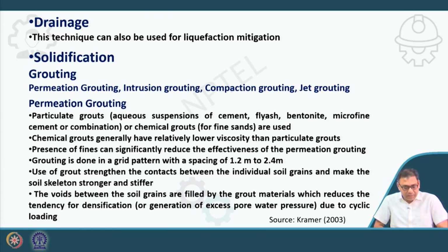Okay, so that means in permeation grouting, the particulate grouts, for example the aqueous suspensions of cement, fly ash, bentonite, microfine cement or the combination of these, or the chemical grout used for fine sand, are used for this grouting technique.